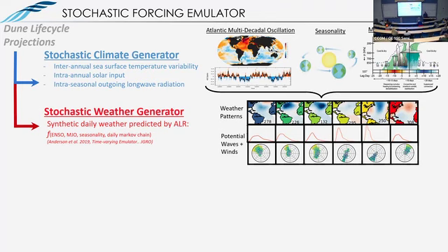And what we find when we can do that is that we can describe potential outcomes for different weather types in terms of what environmental forces look like. And those environmental forces can include wave height and wave period and wave directionality and wind speeds and storm surge and non-tidal residuals. So we can do this with basically any environmental characteristic, shown here by some example probability distributions for different sea level pressure field patterns.